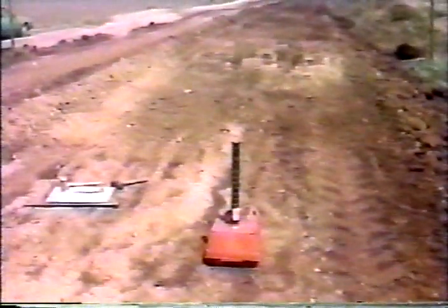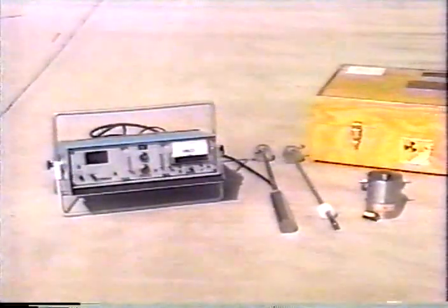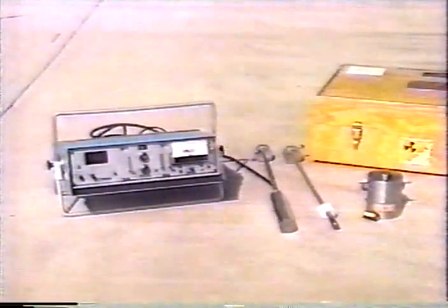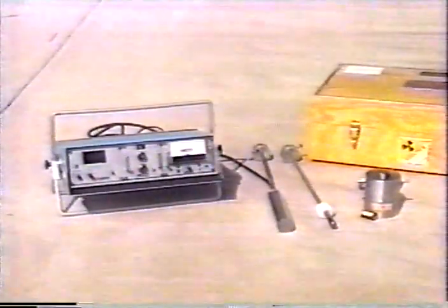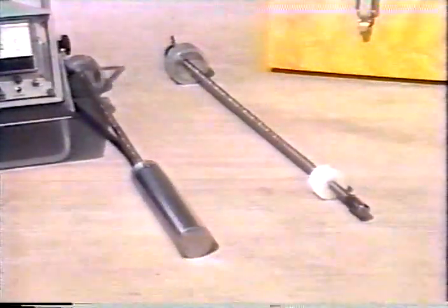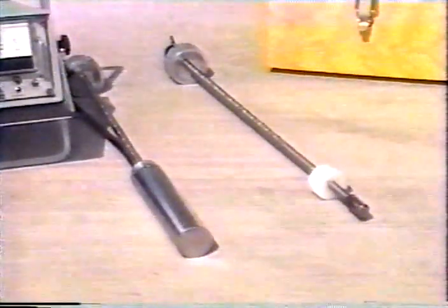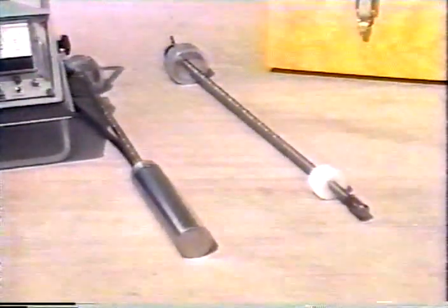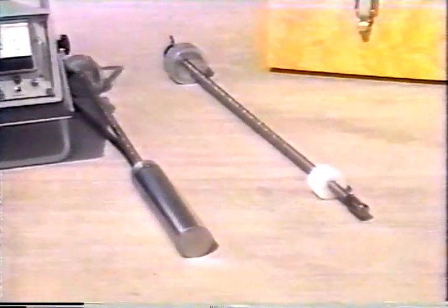Initially, conventional gauges with single probes, the kind used in monitoring soil compaction and asphalt density, were used for monitoring concrete density. Those gauges, however, had their limitations, as discussed in the user's manual. To overcome the limitations, a twin-probe nuclear gauge was evaluated for field use. Indications are that commercially available twin-probe gauges, with certain required modifications by the manufacturer, work well for monitoring concrete density.